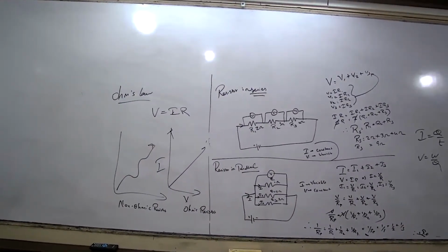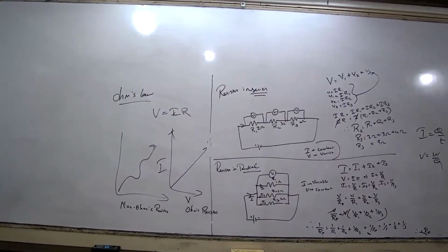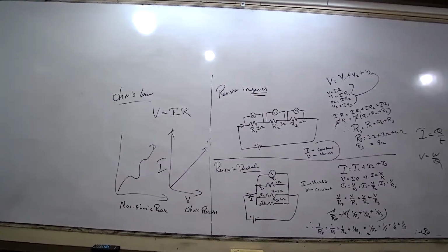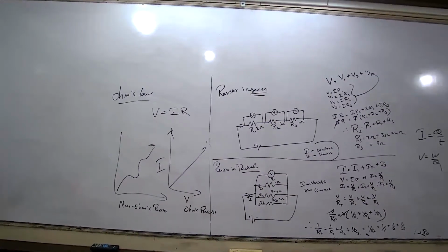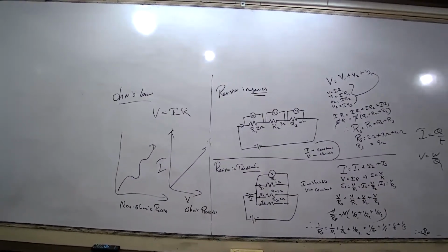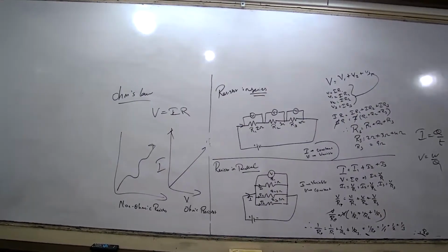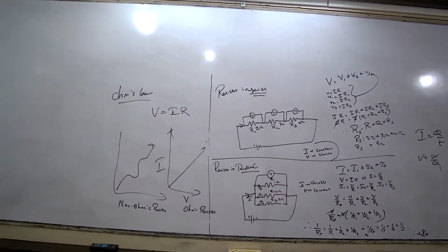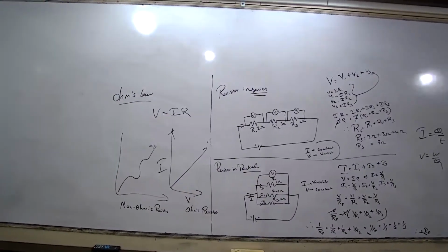By seeing the circuit, you have to minimize it. You have to know how to redraw the circuit by simplifying it. First, you can take the parallel parts, put the formula and make it series. Then in series, you can add them together, isn't it?